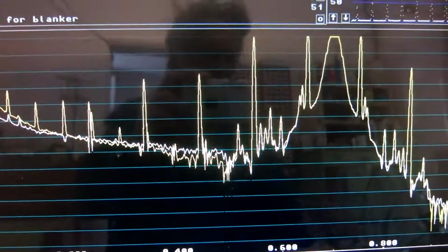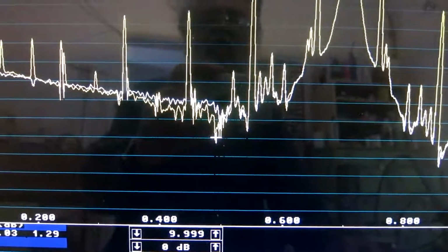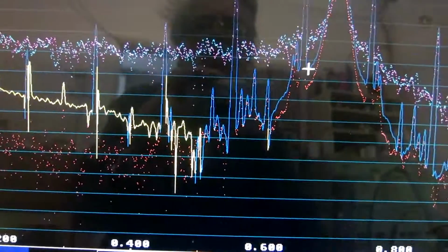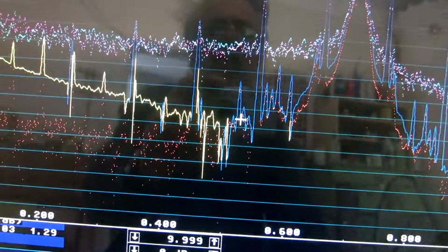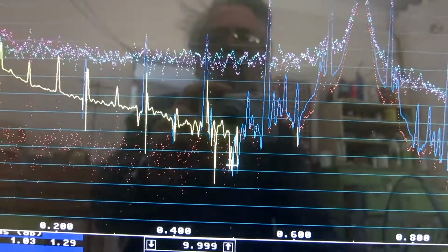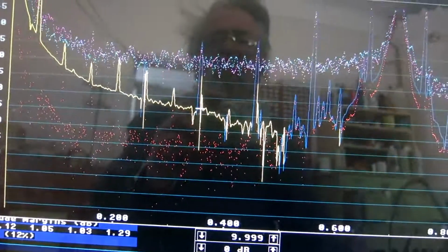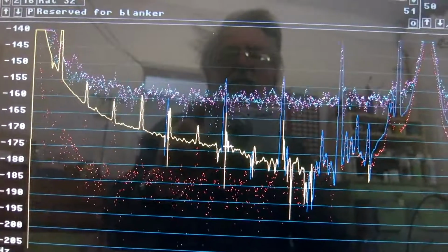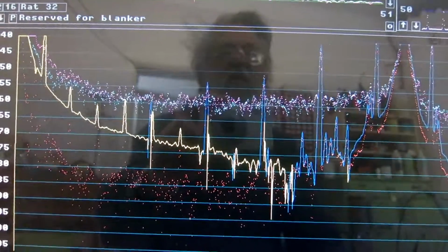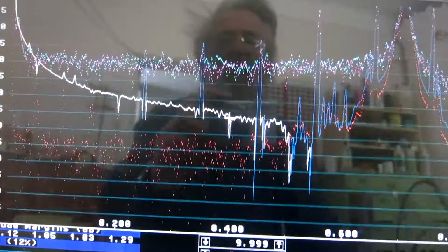It is more obvious now than before that the result here, minus 180, minus 185 for the phase noise, cannot be correct. So I click at the details, and yes, at this point we have the negative contribution from the DC that cancels the positive from the oscillator and creates 0, roughly. I cannot measure accurately above about 350 Hz. I need a 10 dB separation between this curve, the real part, and the imaginary part to trust what I see. This is phase noise, and here is amplitude noise. Amplitude noise should be okay up to about 400 Hz.